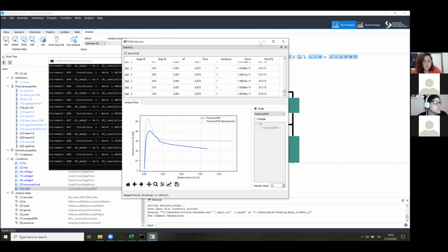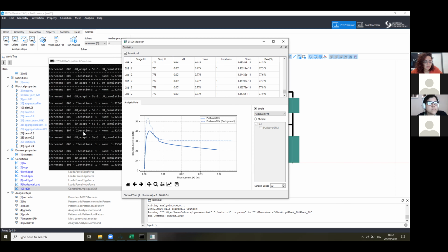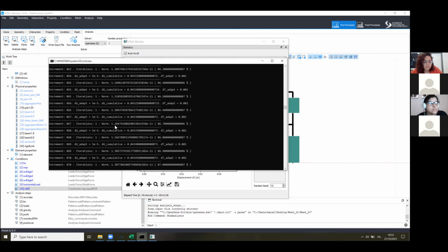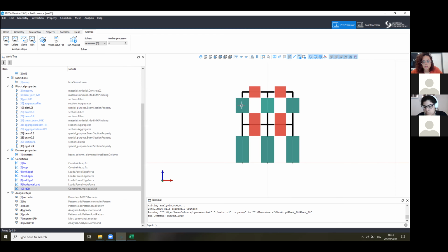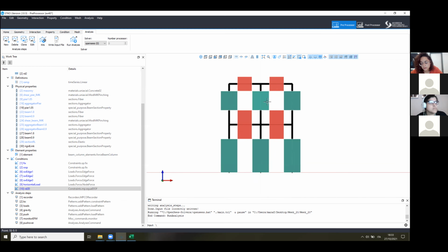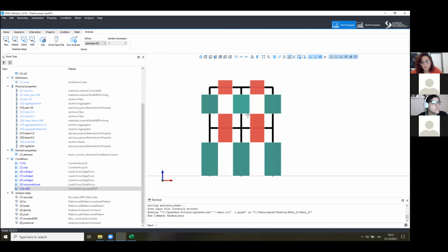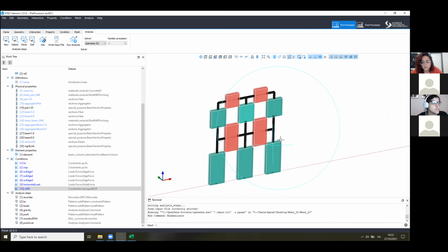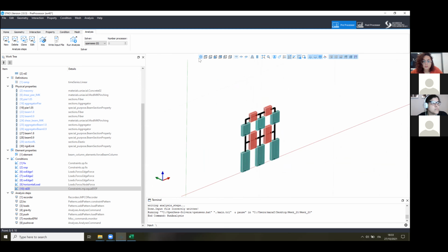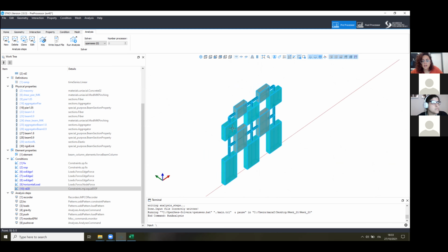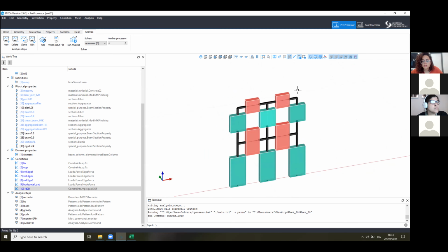There's not really much that I can tell you about. This kind of analysis is quite easy. It's not really so complicated, considering that we did 3D analysis on frame structure, large pushovers, nonlinear time history. So the analysis is not complicated. The most complicated part is to understand how to simplify the geometry, especially if your structure is not regular. And so if the equivalent frame method approach is feasible for your structure. And second of all, how to calibrate your material properties.